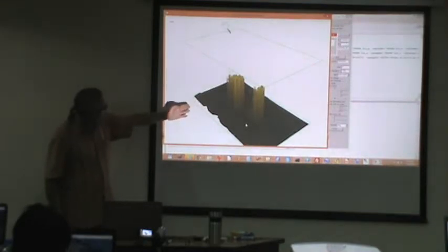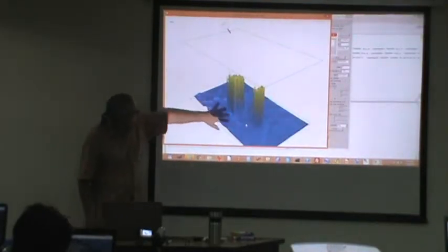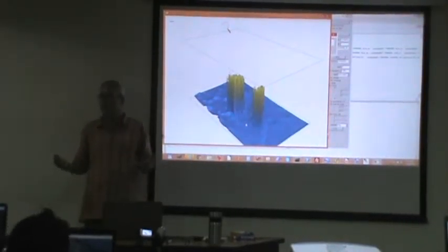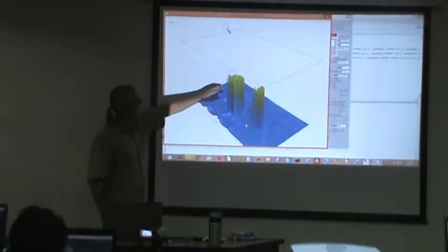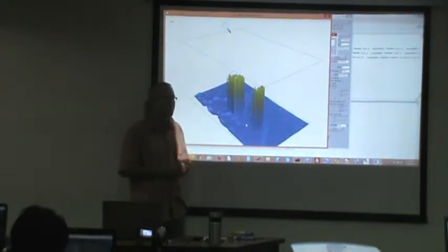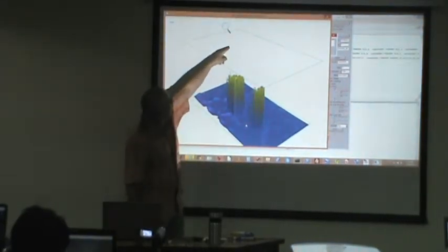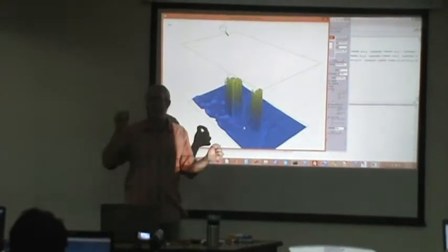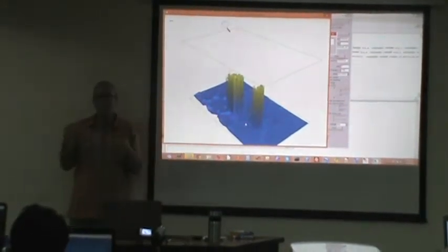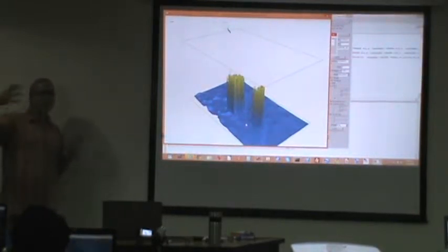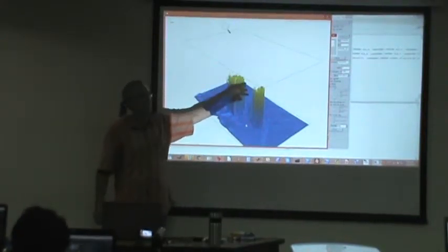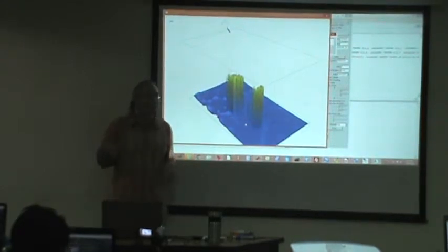But if you look, I mean, it's totally destroyed, right? By the clouds. But these clouds are so dense, they look like actual structures. They're not just like these individual points. Those are easy because they're very far away from anything. But these form structures. So if I say with the filter, keep all the points that don't have any points in 10 meters, well, these have plenty of points in 10 meters because we are scanning the clouds.